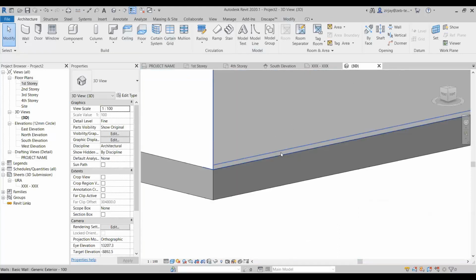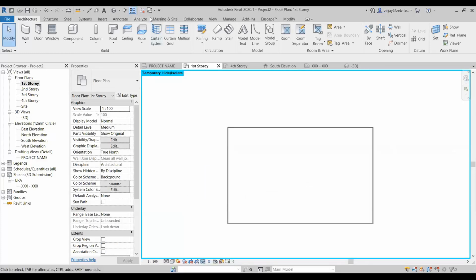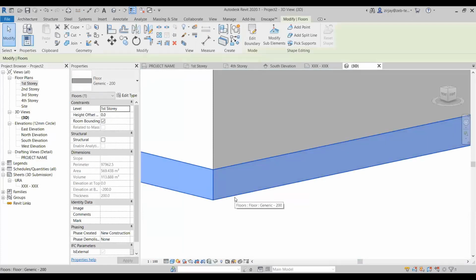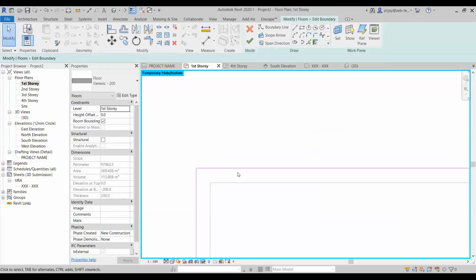So DJ, I have a question. Okay, yep. When you use a middle line indicator, and then when you use the 100 of serial, the center line of the wall. Yeah. Okay. When do you use the center line and when not to use it? You know, on what kind of situations? For floors, we always go to the exterior side of the wall. Yes. We never stay on the. But if you're asking why I use this particular method, yeah.